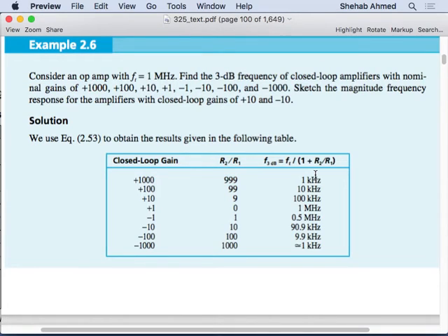R2 is much larger than R1, right? So then you have a large time constant. Large time constant means more time to process the signal, because for voltages to rise and fall, it will take time. So that means you're going to be limited to low frequency signals passing through this amplifier. I'm just trying to explain the physics behind it, and that's basically due to the capacitor in parallel.